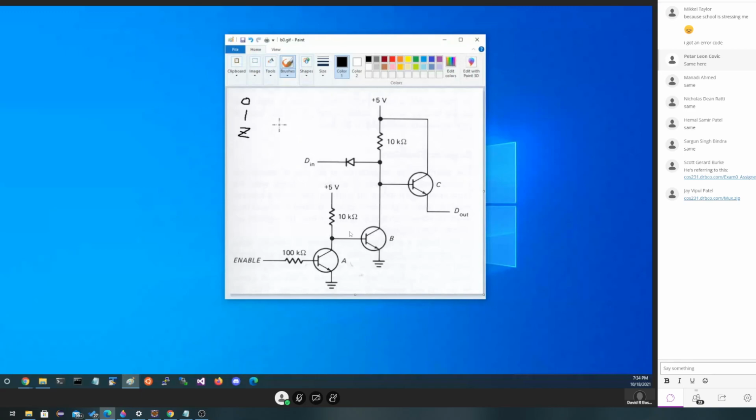So that's the third choice you could have on an output, right? The output's putting out a 0, it's putting out a 1, or the output isn't even there. Now, it may physically be there, but as long as it's putting out a signal from which I can't source or sink current, it's effectively not there. So this is the way an output might look on a buffer, being a device that just simply takes a regular 0 and 1 signal and turns it into one that can be 0, 1, or high impedance. We sometimes also call this floating. Floating means we're not giving out a valid value, and we're just kind of hanging around.